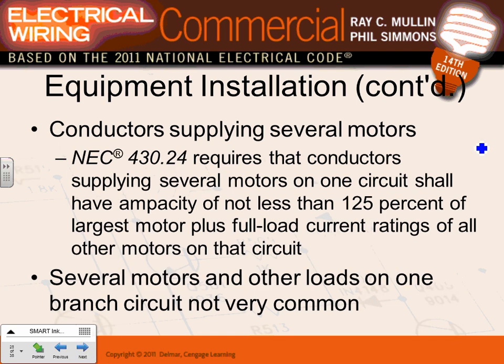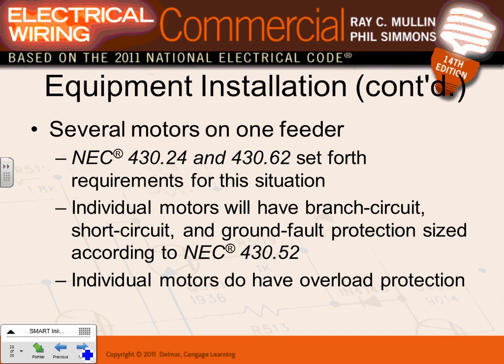If you have a conductor supplying different motors, guys, on one branch circuit, not a good idea. You have a branch circuit that feeds multiple motors. You take the largest motor, increase it 25%, plus full load of all the others. Does that sound familiar to you guys? I hope so. We're going to do it again in the next project, do a couple of examples, commercial, but 25% of the largest plus full load current of all the others. It's not a good idea to put multiple motors in a commercial building on one branch circuit.